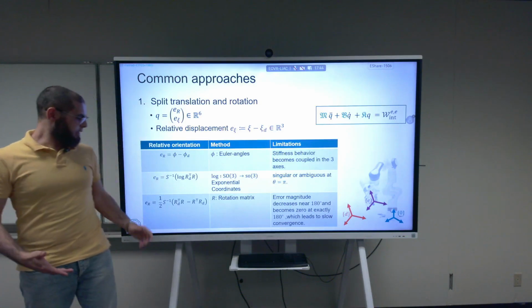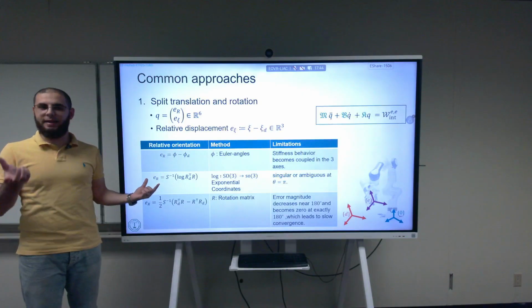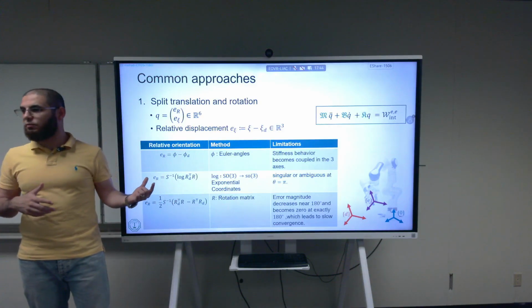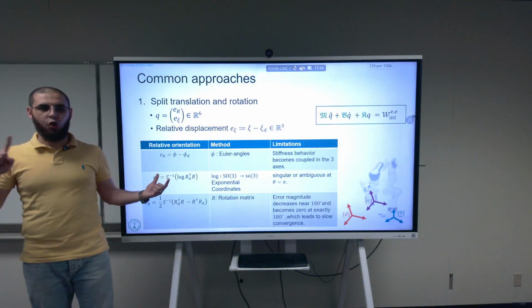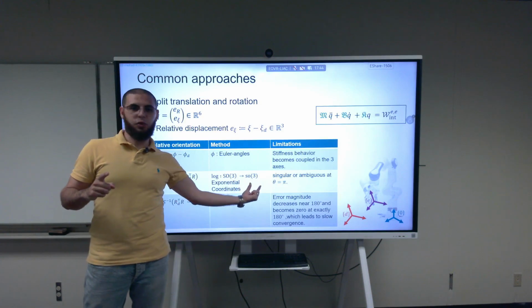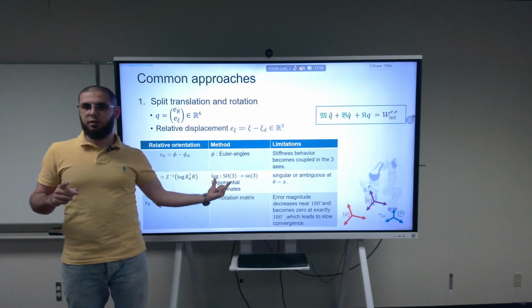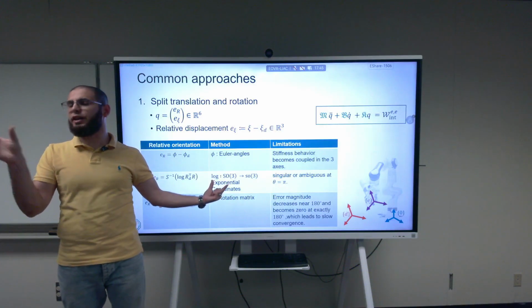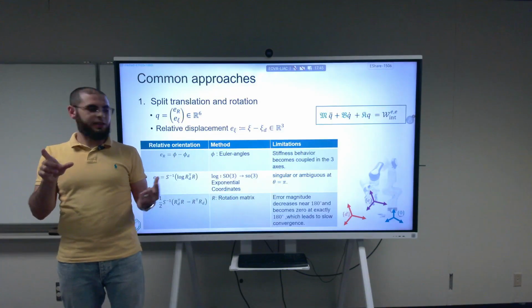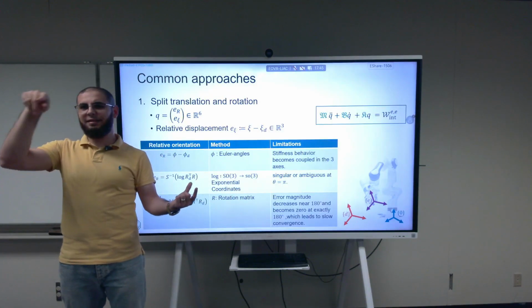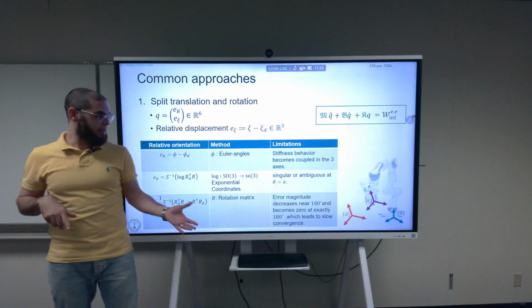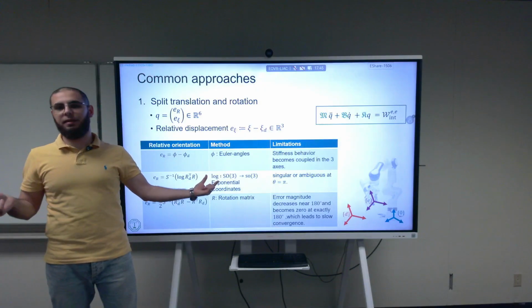An alternative is to do it a little bit geometrically, with something we've already talked about, which is the exponential coordinates. We said the exponential coordinates take you from small so3 to big SO3, right? This is how we used it, with the Rodrigues formula. So the Rodrigues formula, you give it the n, if you remember the n tilde, and it will give you the rotation matrix with a theta. The log is the inverse of that map.